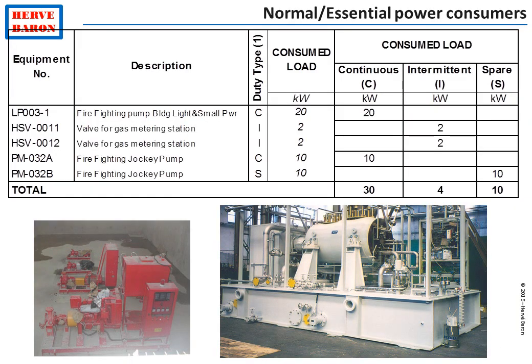The plant power generators are fueled with gas from the process. In case of process upset or shutdown, the fuel gas to the power generators is stopped and the generators shut down. Some consumers need backup power. These are, for instance, the auxiliaries for rotating machineries, which must remain operating after the machinery is shut down to cool it down. Another example is fire water pumps.